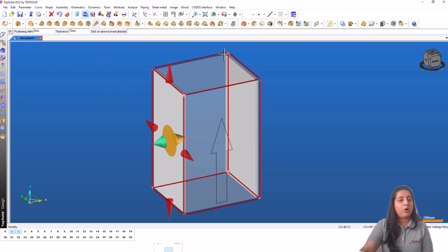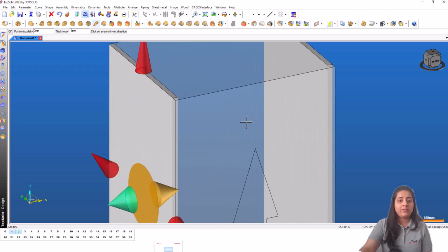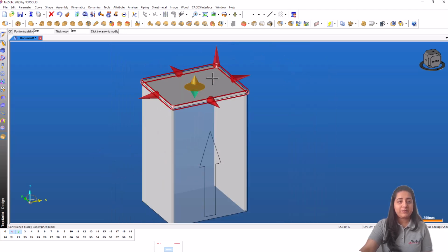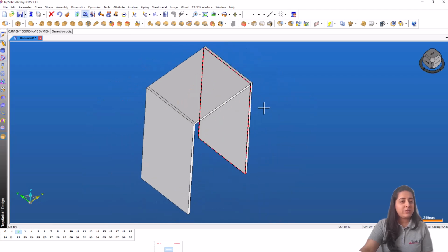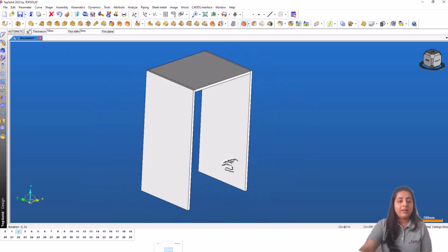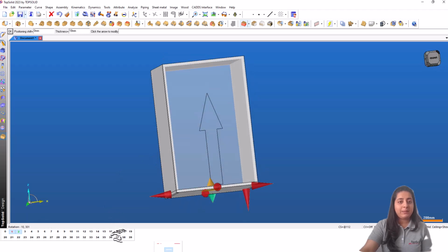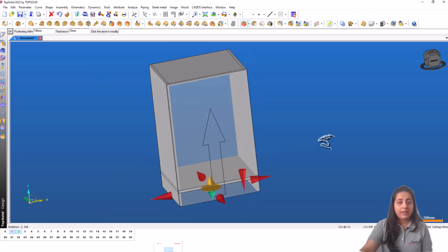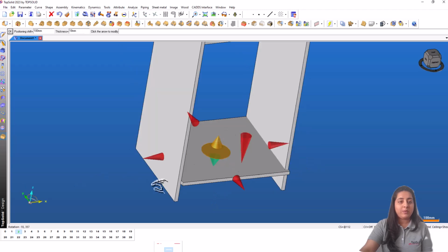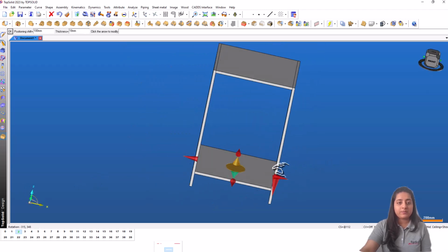Same method applies for all the panels here. Only for the bottom panel, I am giving a 100 mm shift in the positioning, leaving space for skirting. Okay. Once I have this outer structure ready, I am hiding the driver block. And now we'll put the back panel using manual selection of the planes.